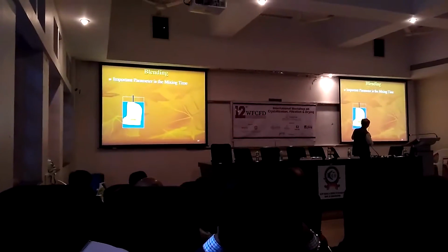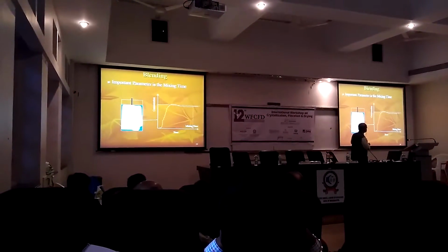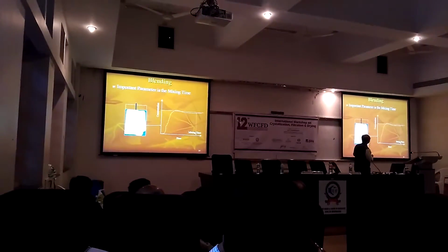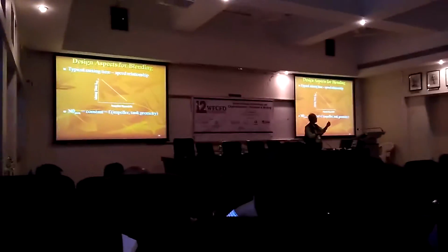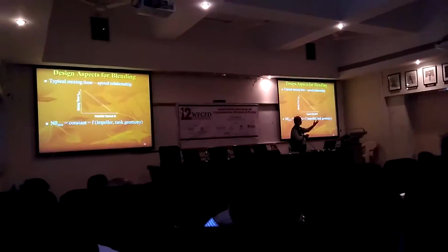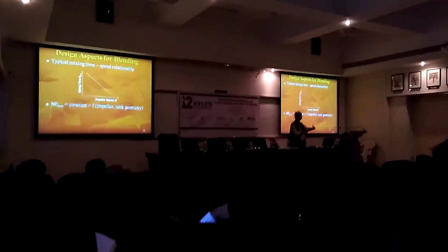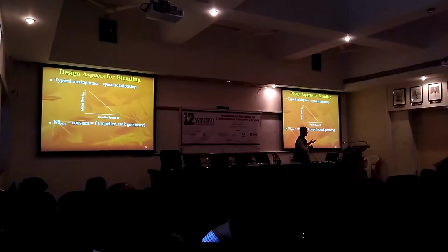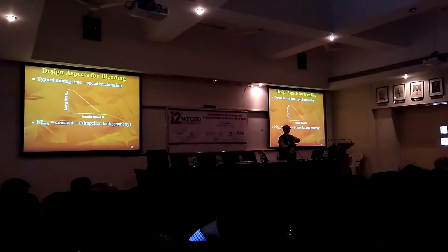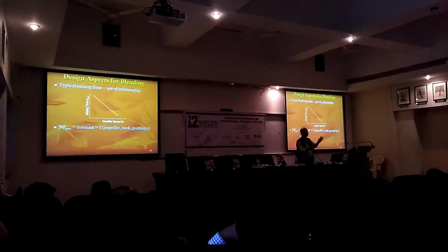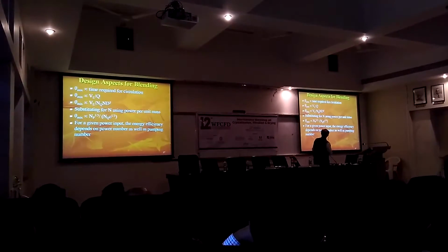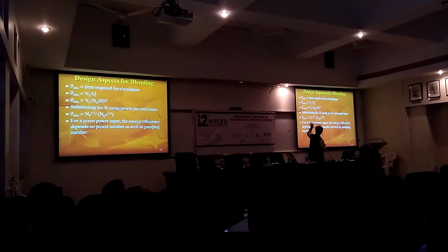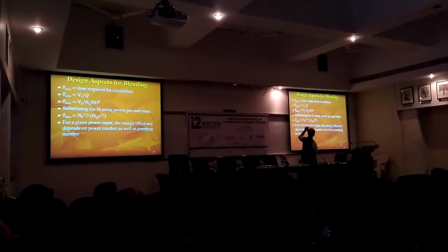So this can be calculated by actually imagining this. You have added the material, it is spreading, and then you can estimate this by actually measuring a mixing time, which can be correlated by using what is known as a dimensionless mixing time, n into theta, theta being mixing time and n being the impeller speed per second. So mixing time in seconds, impeller speed per second, it becomes a dimensionless mixing time, and this dimensionless mixing time could be a good scale-up parameter when you want to duplicate the systems which you have studied in a lab scale to an industrial scale. Again, you can calculate this values in terms of how theta mix can be estimated.